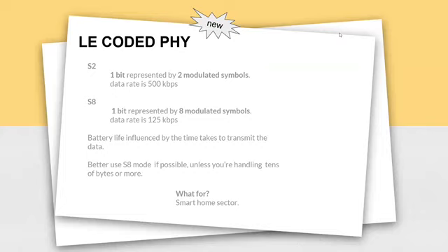But do you really get lower power consumption in your application now? Not necessarily. Since the data rate is now lower, the connection could be held for longer. Connection demands a lot of power when it comes to IoT devices, so you might end up waiting for the entire data to be received and wasting precious battery life. Make sure to create really good benchmarks testing your use cases.